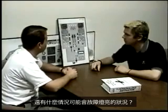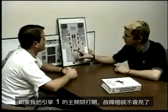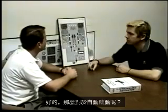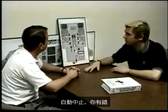Is there another time when you might get a fault light? Sure, if I brought the engine 1 master switch up, the fault light would no longer indicate that FADEC problem, it would indicate an abnormal shutdown. Okay, so for auto starts, auto start faults, hot start, auto abort, you get a fault light.